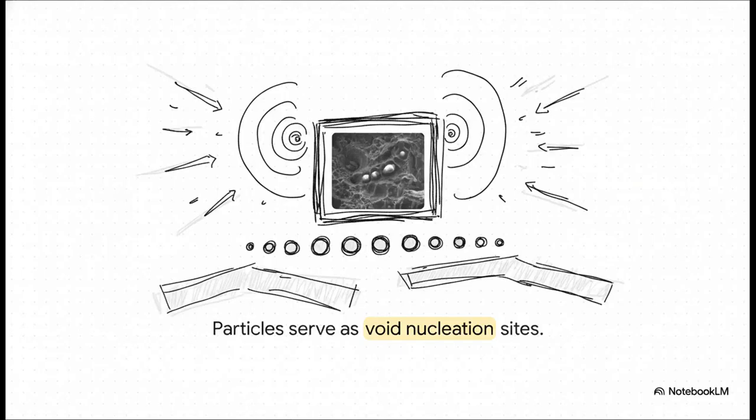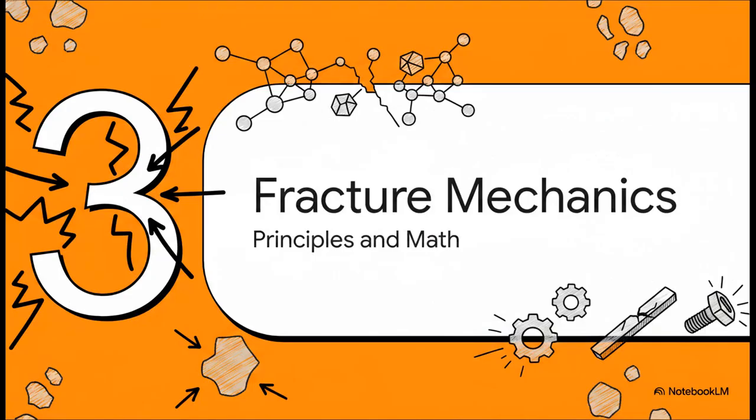This electron micrograph is amazing because it actually catches the crime right in progress. Look at the center of those craters. It shows us exactly where those tiny microscopic voids nucleate around hard inclusion particles inside the steel. These hard particles are usually just microscopic impurities left over from the manufacturing process, which really highlights why material purity is such a massive deal in metallurgy. As the softer metal pulls away from those impurities, empty voids are born, ultimately linking up into a catastrophic structural crack.